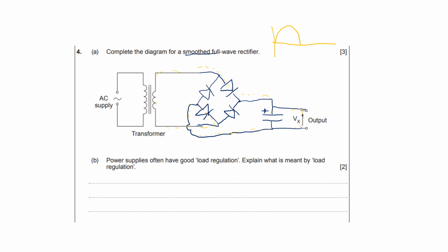And for the reverse half of the cycle, let's use black, it'll be coming this way, and we're going that way again, also through this way, back, and then back out that way this time. So it will be flipping the signal up from the original signal. The original signal you have would be obviously 1.4 volts higher than that. We're going like that, yeah. So you can see the idea of it flips the signal up. That's how it rectifies it.